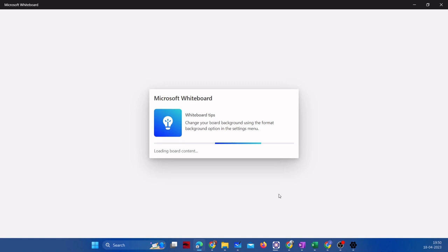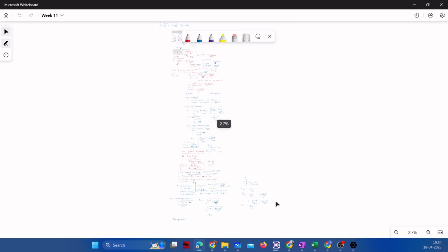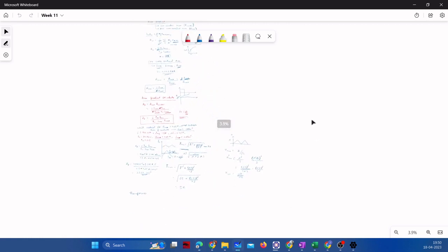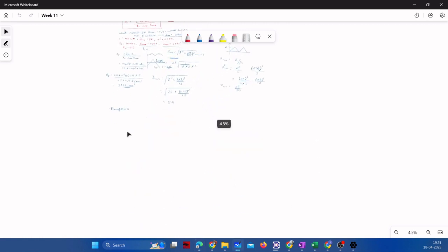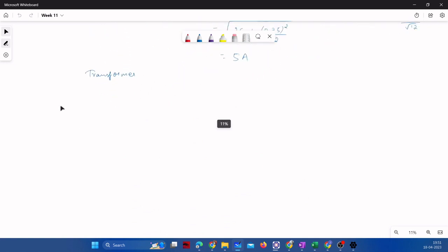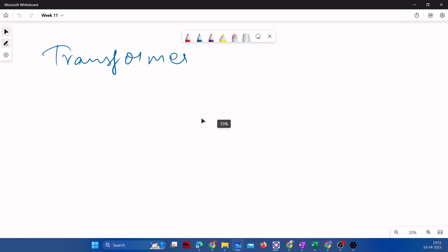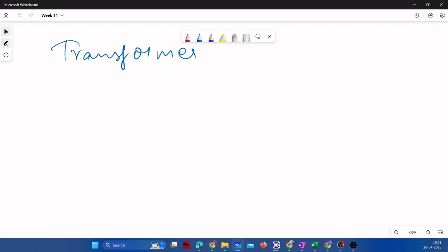So design window area will be the same for both the devices, as I told. It will be the same in the case of transformer as it was in inductor. The thing is, the core area expression will be changed slightly, that we will see. So core area was nothing but dependent on peak flux divided by maximum flux density.